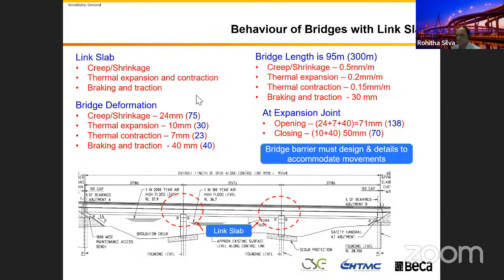And then I talked about many bridge types. When you build bridges like flyover bridges, you see we have an expansion joint at every pier, but to avoid that, we use the link slab system. With the link slab, there's a limitation on how far you can push your expansion joint distance. The calculation is based on creep, shrinkage and thermal deformation in the bridge. So you need to use that knowledge to solve your design problem in that assignment.